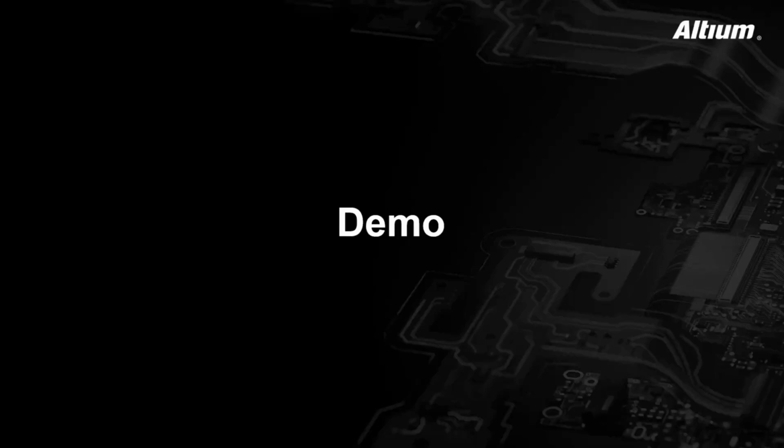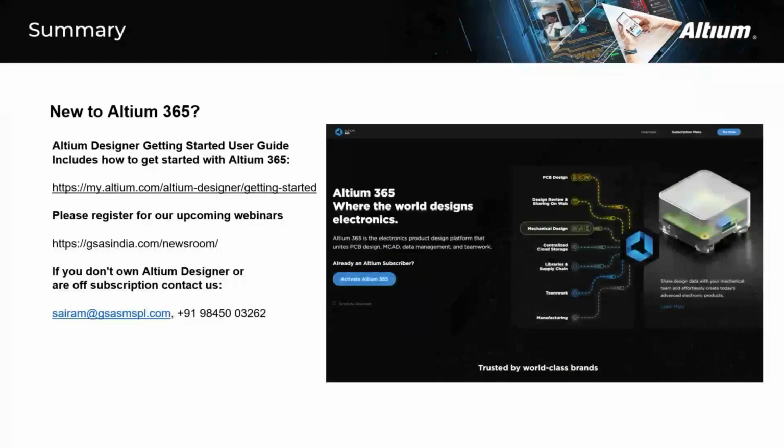Yes, this is all about the advanced routing and techniques webinar. Now, to summarize our session today, we have showed how we can define the differential pairs in the schematics and how we can do the routing, and how we can also define the differential pairs in the PCB data. We also showed how, if you have identical differential pairs, we can do the routing for the group of two nets and then copy and paste the same.